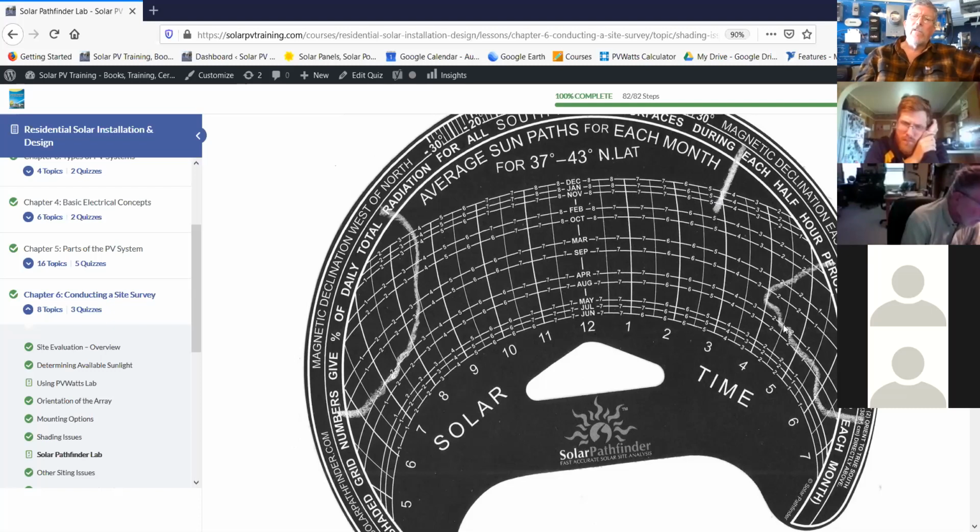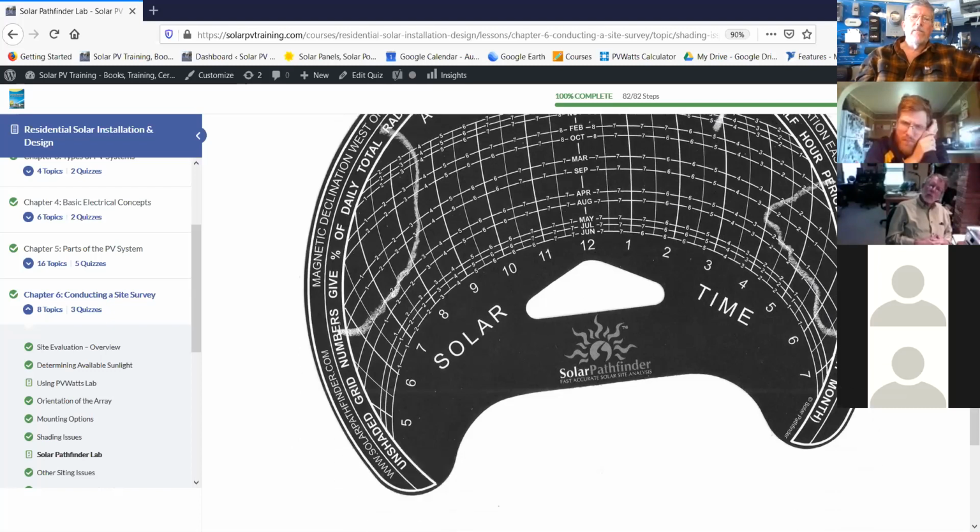And the pole here only affects us a little bit in the mid-afternoon, but only in the winter time. And this over here affects us. So by looking at it, you can get a visual of where the array is going to be shaded when, 24 hours a day, 7 days a week. Okay, so any day of the year, you can go out and take this reading and it's going to tell you where the shading is going to be occurring.